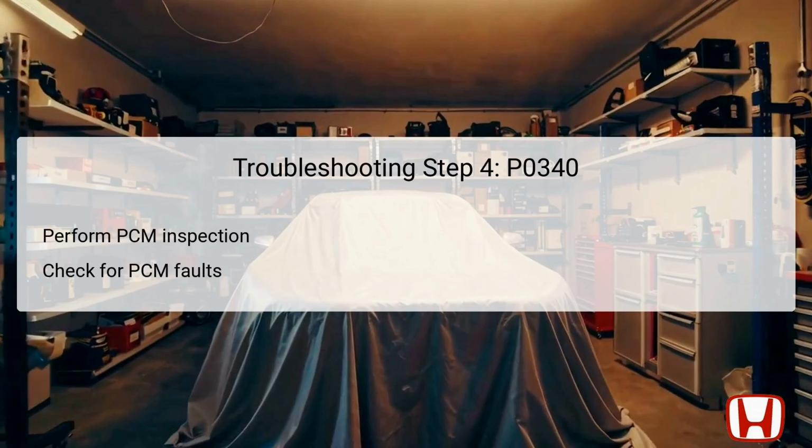Upon confirming that all circuit inspections have returned normal results, you must proceed to inspect the PCM itself as the final step in diagnosing P0340. This step is critical because although the PCM is usually robust, it can still malfunction and lead to the symptoms observed.